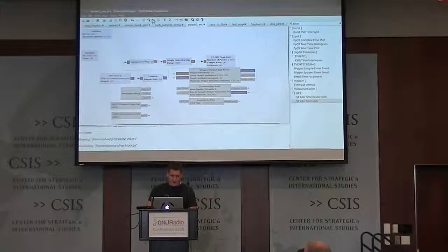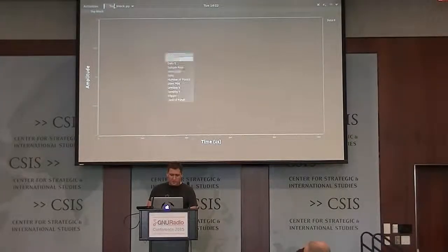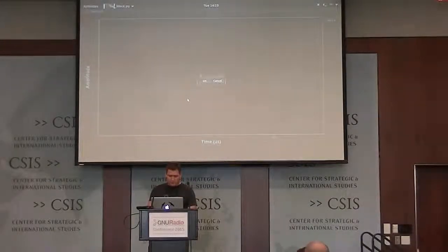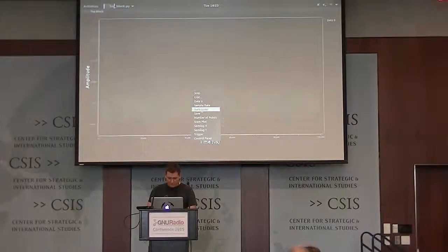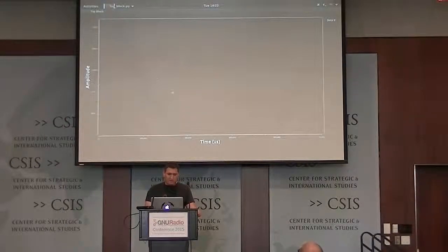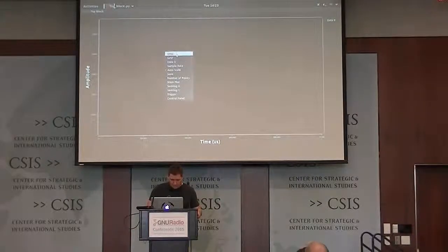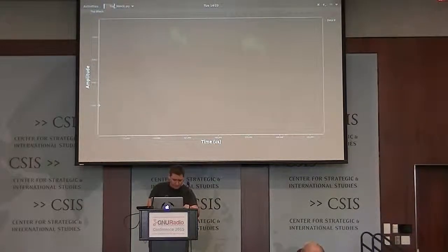If we look at that graph, we're basically creating a very simple detection metric for energy. If we look at a bunch of samples, we start to see that when a burst comes along, this detection metric goes high. So this is a very simple energy-based detector. If we stop this at some point, zoom in, and look at the energy level down there, we can pick 0.001, which looks like a reasonable triggering threshold that'll work for this example.